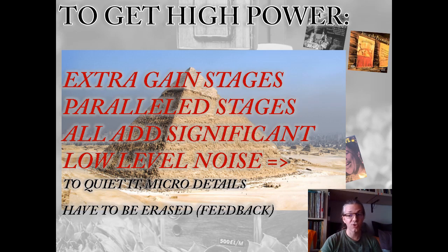So eventually, people use feedback to correct a lot of distortions that the amplifier adds to the signal. But feedback doesn't address that part, when the signal gets lost due to the noise of the stage, where the low level signal gets eaten up by the noise floor. Feedback cannot do anything about that. And it cannot do anything about when you have multiple parallel stages, and because of the imbalance between each stage, they are eating up the micro details. Feedback doesn't do anything with that.